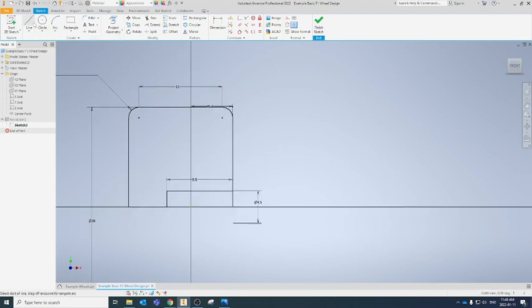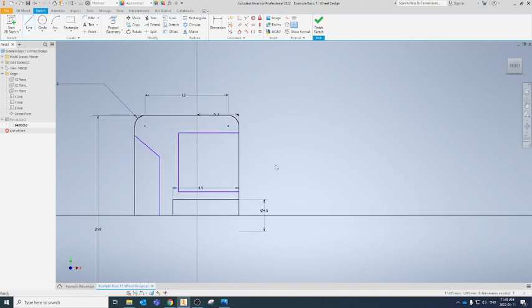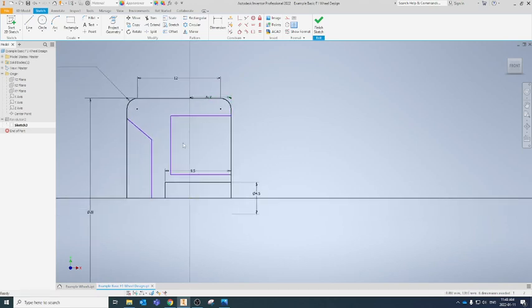What I'm going to do is start a line, and draw some profile shapes in here. Okay, so what I'm going to do here is cut this rectangle you see right here out of the wheel so that it is no longer included in the volume. And I'm going to cut this shape right here out of the front of the wheel as well. So I'm just going to quickly dimension this.